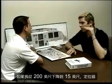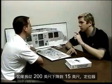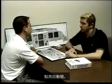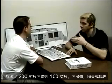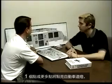If I were to go from 200 feet down to 15 feet, the localizer, if it's lost, or if I deviate by more than a quarter dot, it's going to illuminate the auto land light. And then from 200 feet down to 100 feet, the glide slope, a loss of or a deviation by 1 dot or more, is going to illuminate the auto land light.